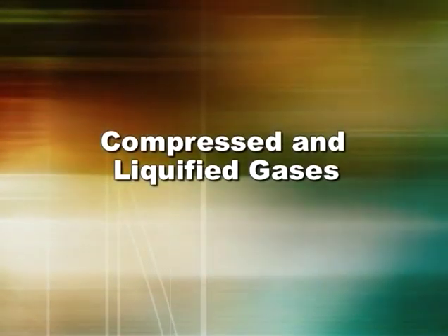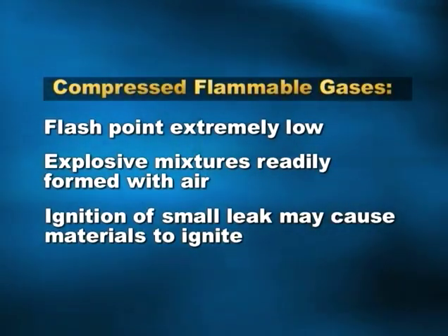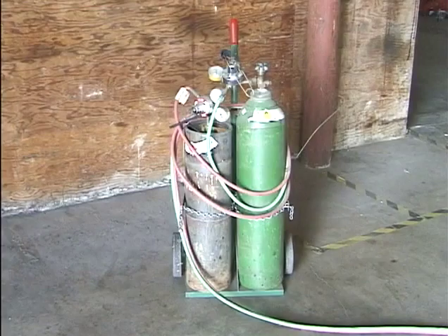Compressed and liquefied gases. The flash point of compressed flammable gases is extremely low and always below room temperature. Explosive mixtures are readily formed with air. Ignition of even a small leak may cause the materials to ignite. To avoid fires resulting from ignition of compressed gases, never roll or drag cylinders when gases are stored, transported, or used. Use a handcart or truck specially designed for gas cylinders.